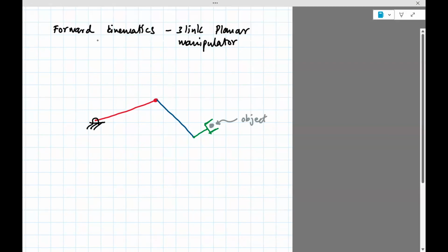So in this case, there's a convention used to determine angles. Theta 1 is the angle made with the horizontal. Theta 2 is actually the angle made by the first link with the second one. It's a relative angle. This is the way it is shown. It's clockwise, so it's negative theta 2. And then this would be positive theta 3 because it's counterclockwise.